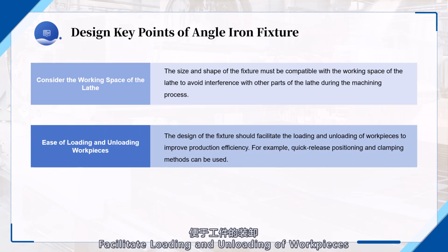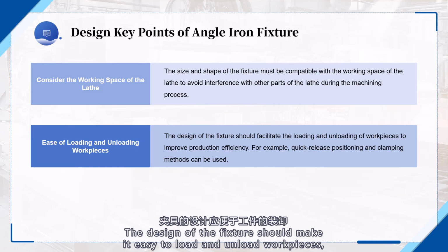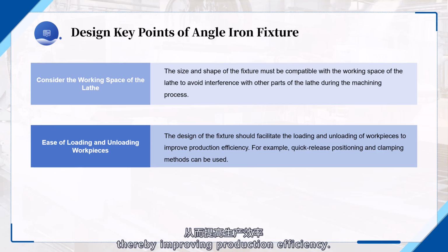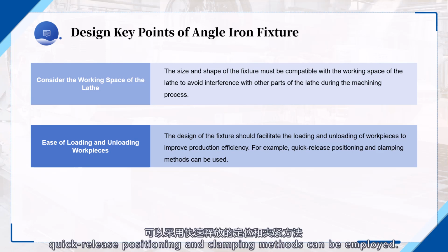Facilitate loading and unloading of workpieces. The design of the fixture should make it easy to load and unload workpieces, thereby improving production efficiency. For example, quick release positioning and clamping methods can be employed.